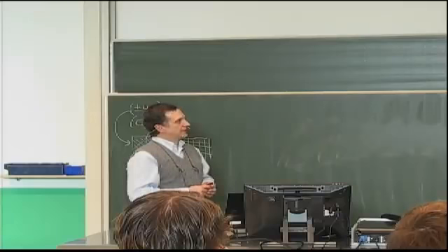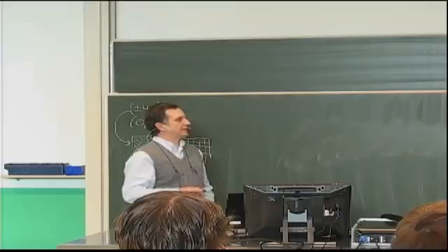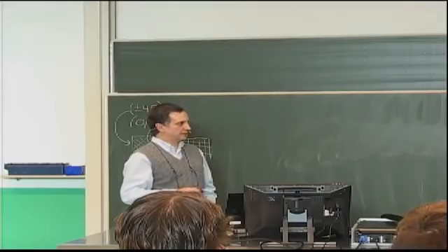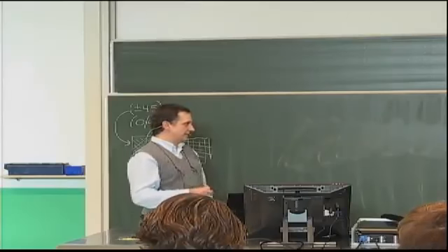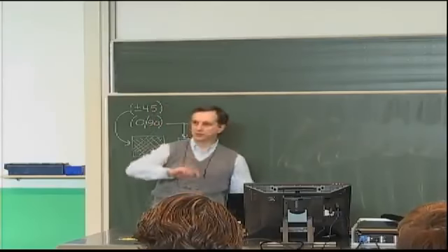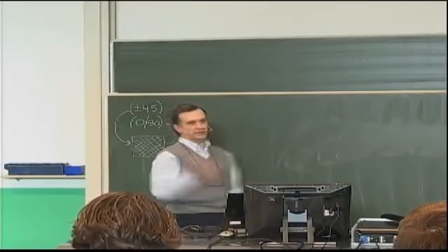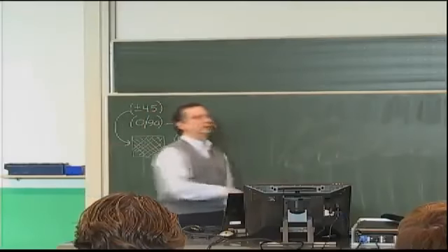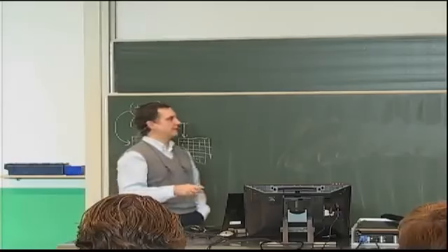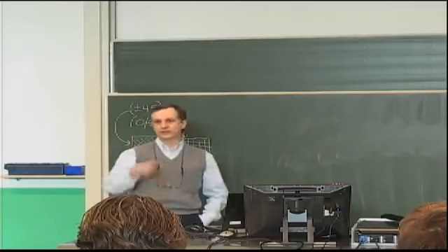case. That allows me to go back to my governing equation at the bottom left here and substitute for w all these derivatives of w. But you can obviously see that these then would give me double summations of sine terms. And on the right-hand side here, I have this peculiarly looking expression, which is just a point force at one location. So the only way to proceed, if I want to insist on this Fourier series business, is to actually replace this with its corresponding Fourier expansion.